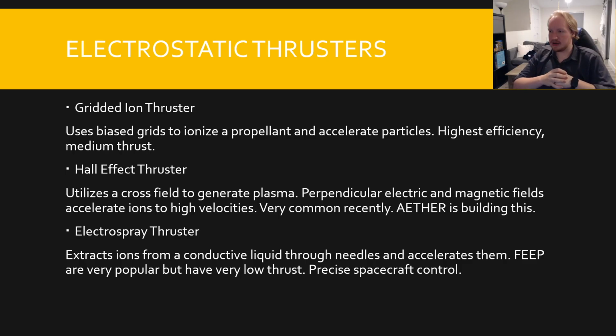They are very popular, not as popular as some of the other options, but they have a very low thrust. They're good for precise spacecraft control, not as much with movement because they have probably the lowest thrust of any of our options here. They also have the benefit, though, of taking a very, very small amount of power to run. We're talking a lot of times in the dozens of milliwatts, so very low amount of power required, which makes them a good option for spacecraft that have very tight power constraints, which we see with a lot of small satellites nowadays.